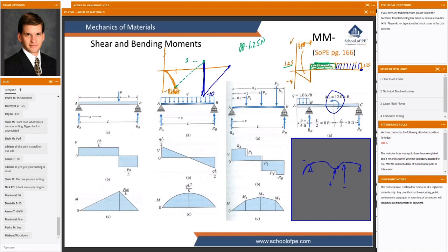So we've got negative bending on the left, negative bending for most of it, until somewhere in here it transitions to positive bending, and then negative bending all the way to the end. And that's true of our diagram. We've got negative bending everywhere except this brief little area to the left of the 12-foot mark. So it works out. It makes sense.